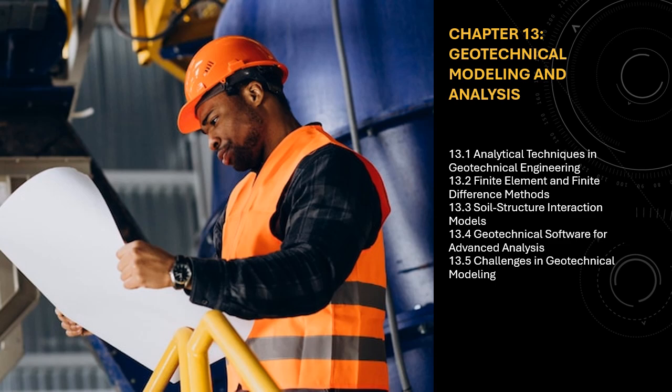13.3.2.4 Boundary Element Method (BEM). The boundary element method (BEM) is a specialized numerical technique used for solving problems with infinite or semi-infinite domains, such as problems involving soil structure interaction. In this method, only the boundaries of the system, the surface of the soil, and the interface with the structure are discretized, which makes it computationally more efficient than the finite element method for certain problems.